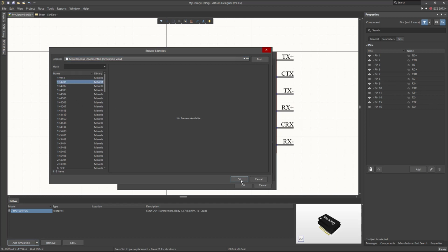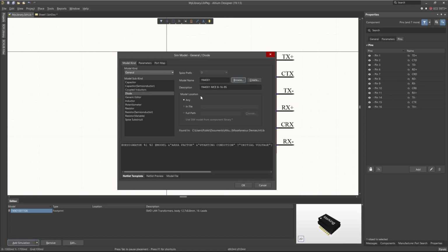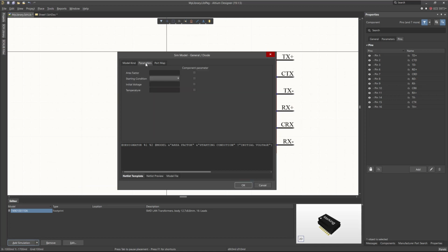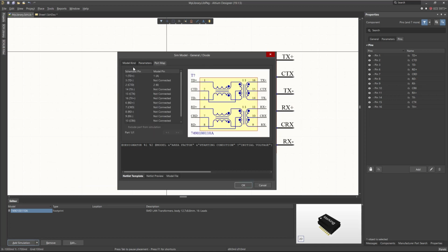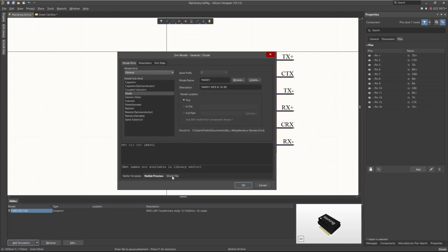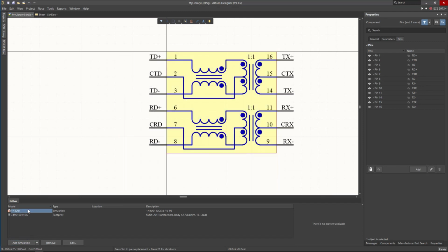If you select, for instance, this diode, it will come up in here, and you will see the parameters and information about this model in the model file. So if it's not one of these models, you can basically copy and paste the simulation model or SPICE model into here to simulate this component, and it will be added in here. So if you added this simulation model, but this is not the right one, let's remove it.